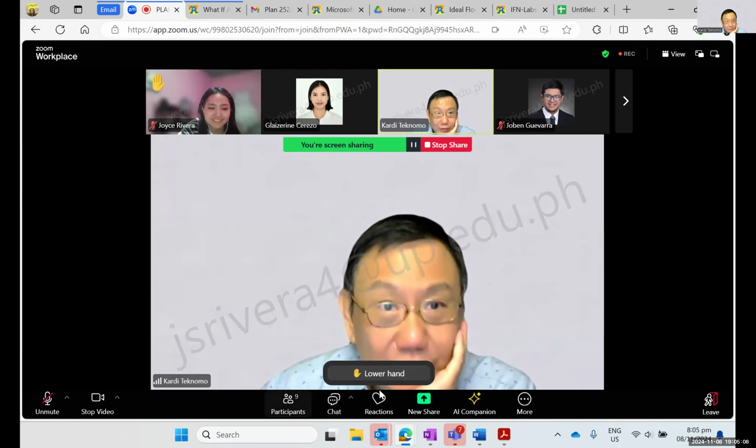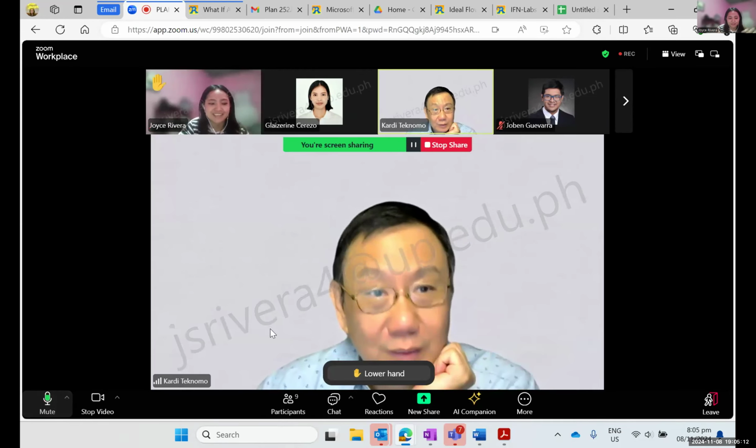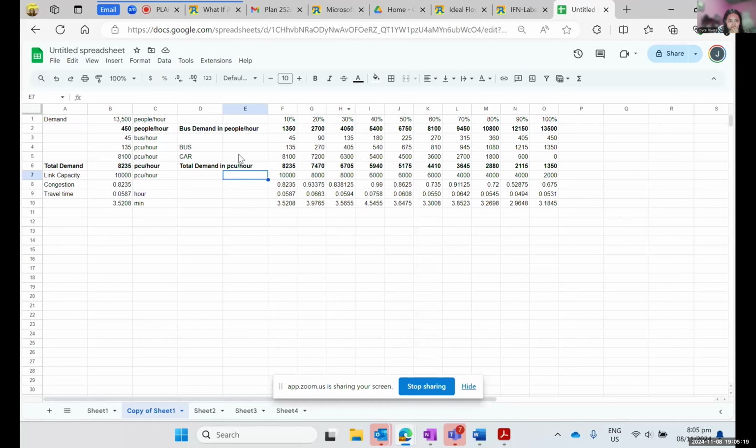Yeah, Joyce. Can I try again? I think I just missed one of the lines. There should be the demand in people per hour, so that's 1,350 for the bus. Then you should divide it by 30 to get the number of buses per hour. And this is the PCU per hour, you multiply it by 3.